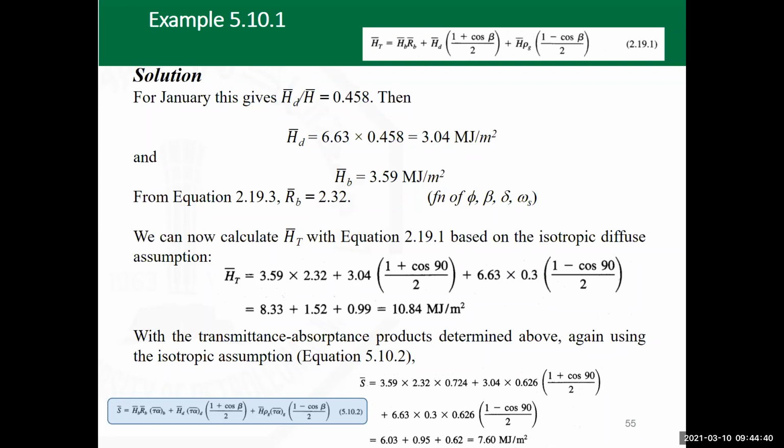So which means that for the same month, regardless of the surface covers, the value of radiation falling will not change. It may change from month to month. Yes, definitely, no doubt. It will change if we change the inclination angle, like instead of beta being vertical, if we change it to 60, to 30, whatever, it's going to change. But if we change the number of covers, HT will not change. What will change is definitely the value of S. And definitely, because of the ratio, the value of alpha tau is going to change as well.